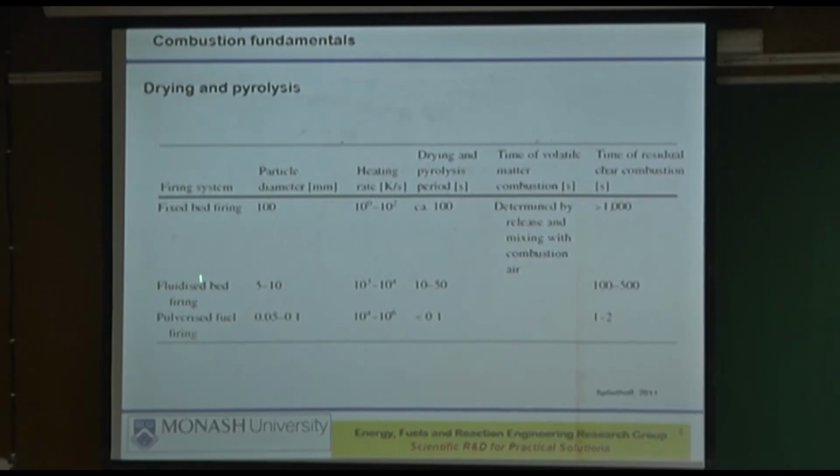That's what every system is dependent on: the particle size that it handles, the heating rate that it experiences, and of course the time that it experiences for drying and pyrolysis, the time for the volatile matter to be combusted, and the time for its residual char to be combusted.